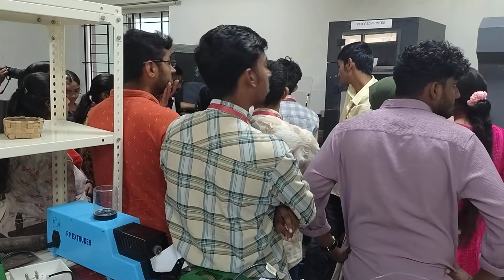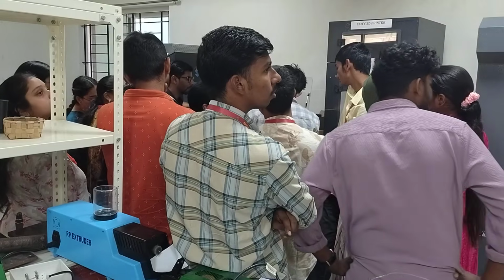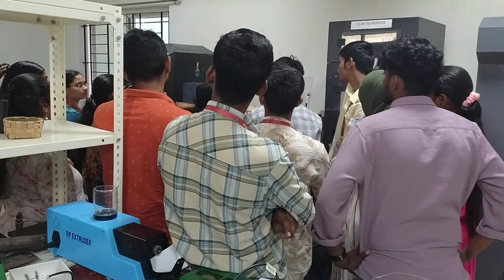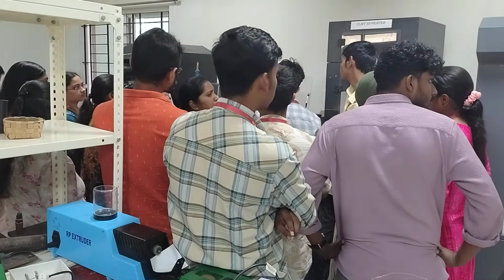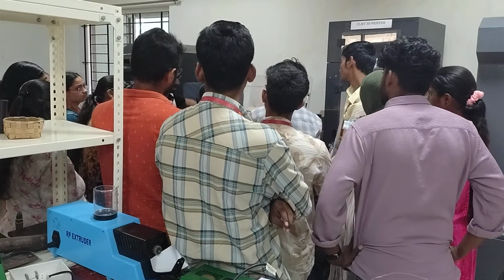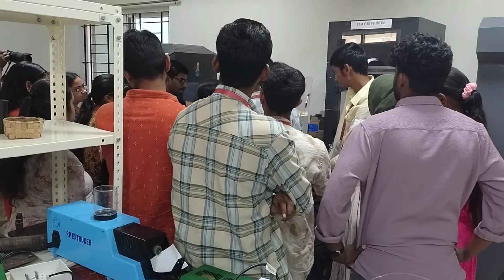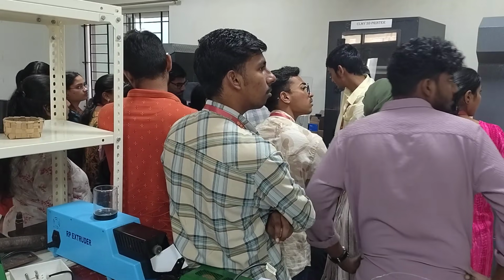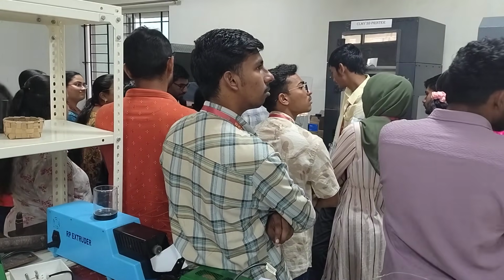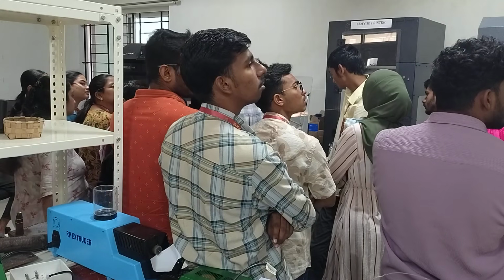Okay, so now it is giving the option quick load or meter load. Now I do not know how much filament is there, so the only option I have is quick load, no meter load. If I know how much filament is already here, I can click on meter load and place it there. So as of now, we'll do quick load. We'll do yes. Now it is asking what type of plastic are you loading?